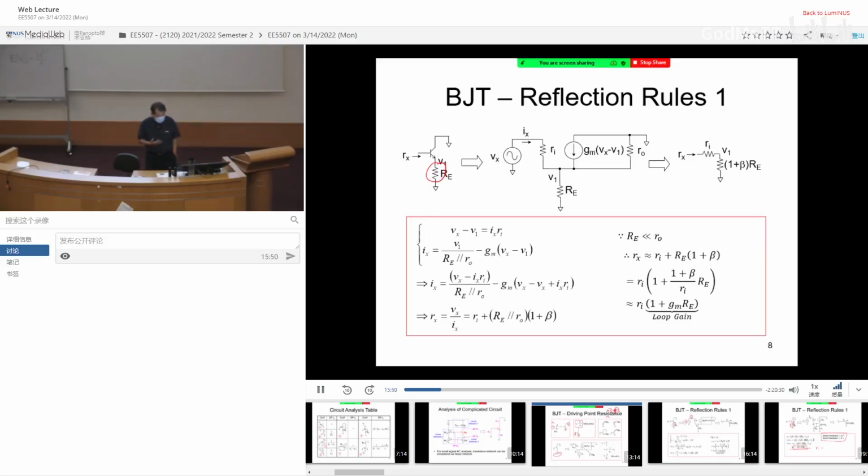Based on this, again, this is the first time I encounter it, so I have to replace the transistor with this hybrid pi model, and then we start deriving, applying the stimulus Vx and observing the current Ix. Of course, I can go through the algebra, and you can see here I list down the algebra. What is Vx equivalent to?